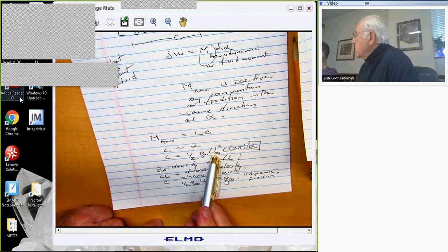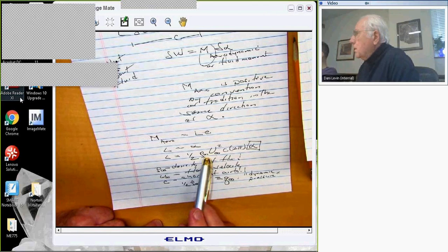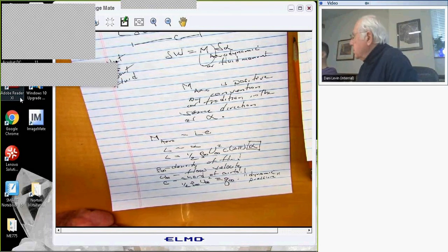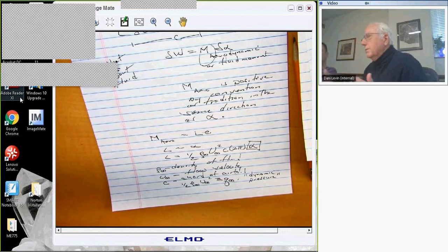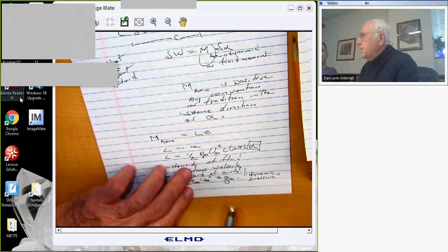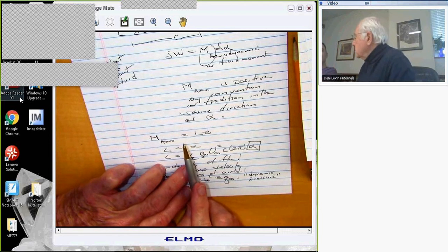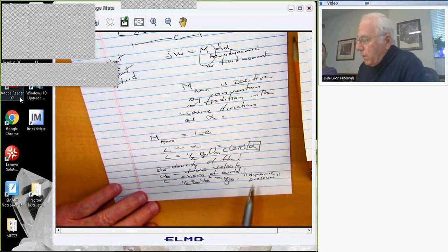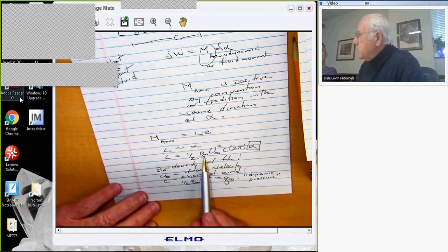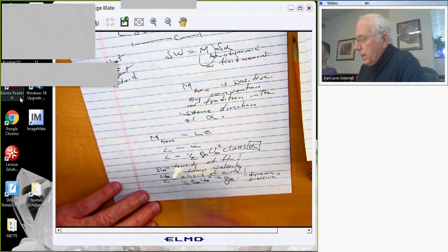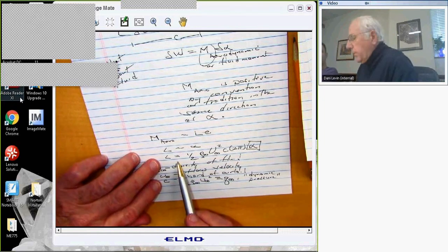Now, in the wind tunnels that the Wright brothers had, they couldn't vary the density. But you can argue on physical terms that the denser the flow, the larger the forces, right? I mean, you don't have to be too insightful to think this might be proportional to rho infinity. Okay, so if you do all this, if you know the density of the fluid and you measure U infinity, you measure C and alpha and all that, and then you measure the actual value of the lift, you can determine what this constant is.